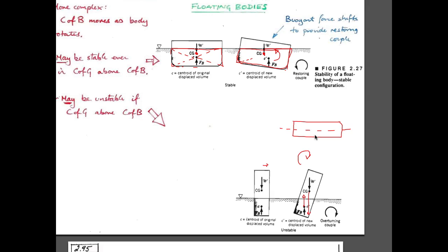Or maybe a bit down, but certainly now you have a center of buoyancy which would be given by this point here, acting upwards. Your center of gravity here would be somewhere off here. And so what it would do is it wouldn't be quite horizontal, but I'd imagine that this line here would be slightly down, and it would be slightly tilted like this, as you can imagine. But anyway, you can use that to be able to talk about stability.